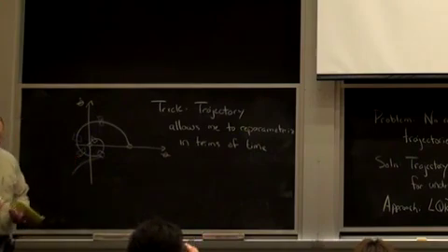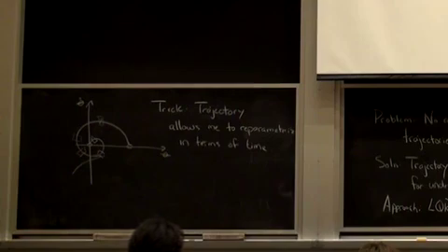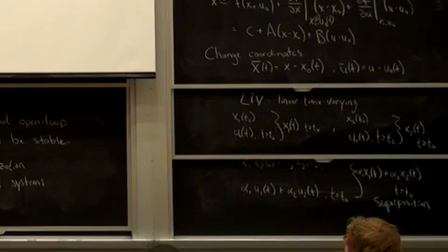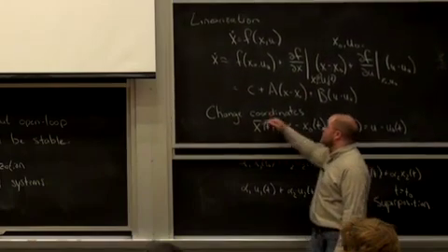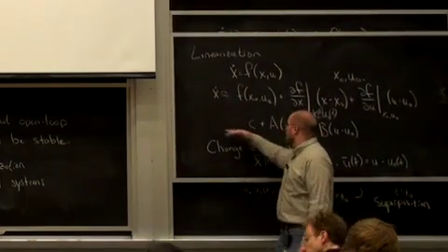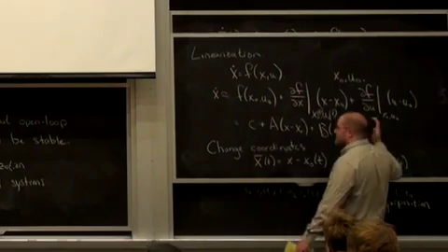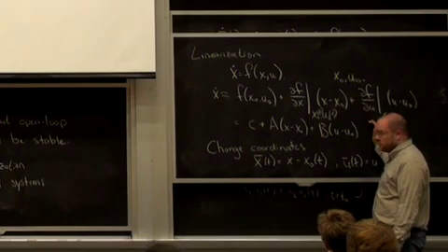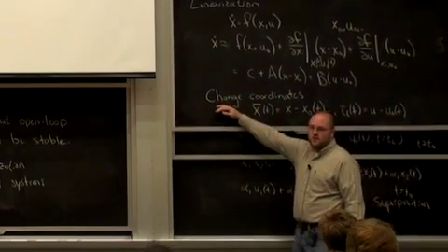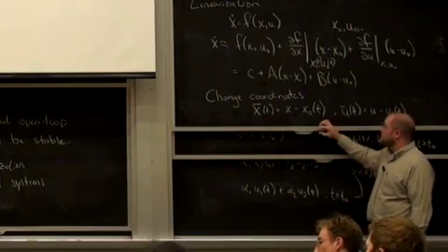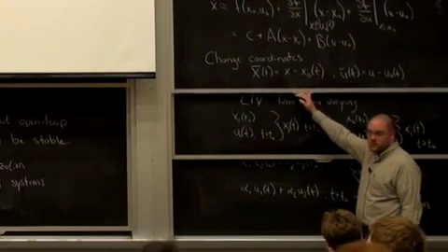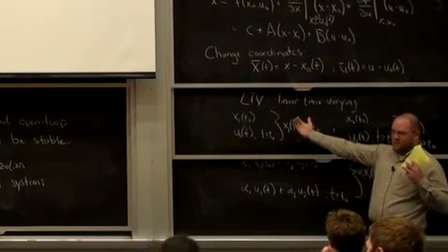Make sense? So I think I missed some closing parentheses here. We talked about how there is a bad way of doing this. If I do a Taylor expansion of my system in the original coordinate system, which is x, then it's not linear. End parentheses. That was the bad way to do it. The good way to do it is to change the coordinates to a coordinate system which moves with the trajectory. If you do that, things become time-varying linear. That was the good way to do it. And that's still an open parenthesis. We're still going.